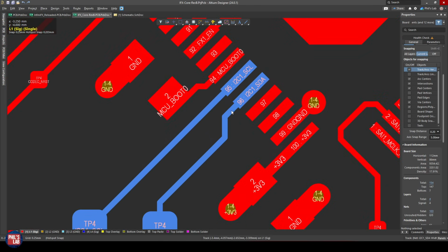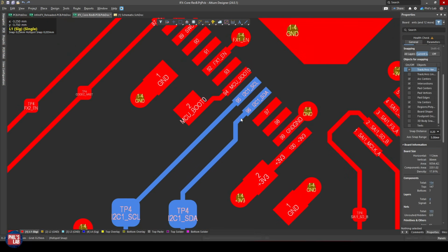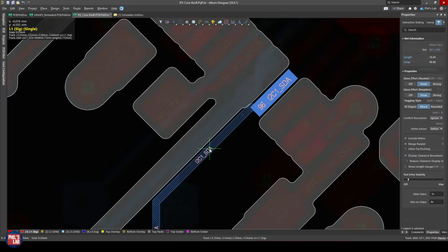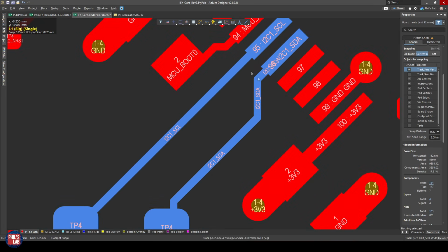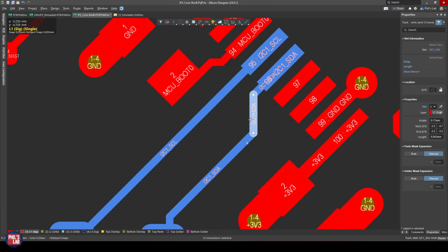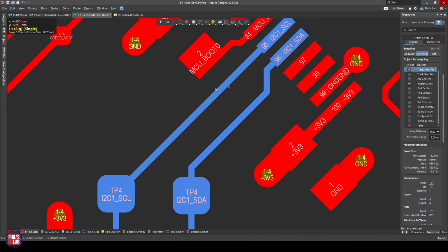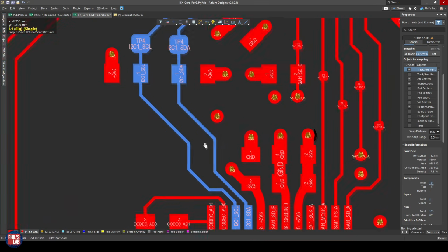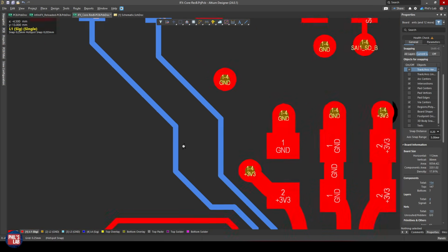The routing itself, I'm just using traces that I use for other signals anyway, so whether this is controlled impedance or not, I'm using the same width of traces. As soon as I come out of, for example, the microcontroller pads up here, instead of sticking close to the other trace like this, as soon as I can, I branch away and I give myself space between clock and data like so. Also, I don't want to route close to other components. I want to give myself space within the I2C interface, but also between other components as well. And I maintain that clearance and that space as much as I can until I have to go into the codec like so. So where I have to neck down, I do, but as soon as I have space, I space them out.